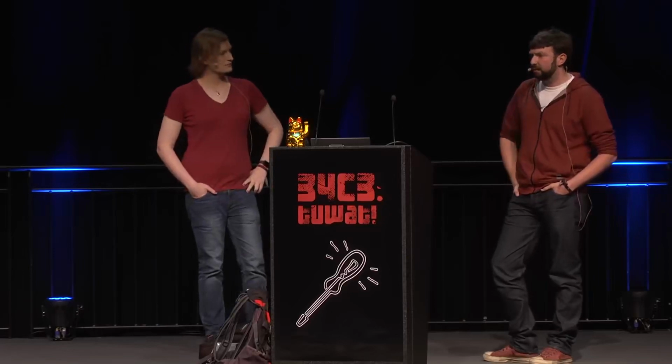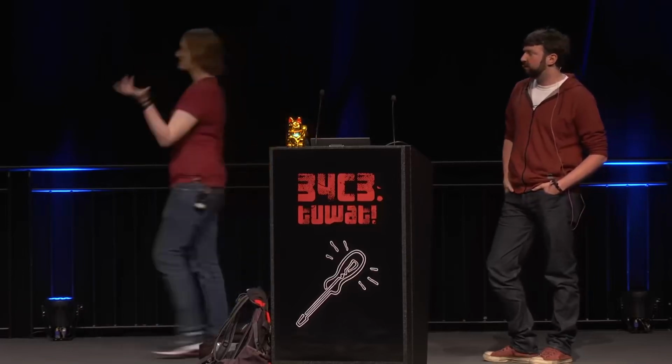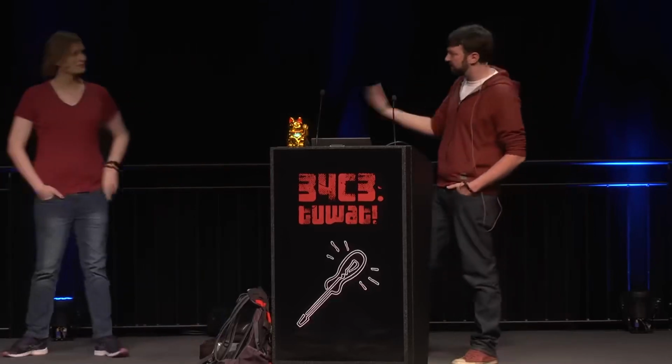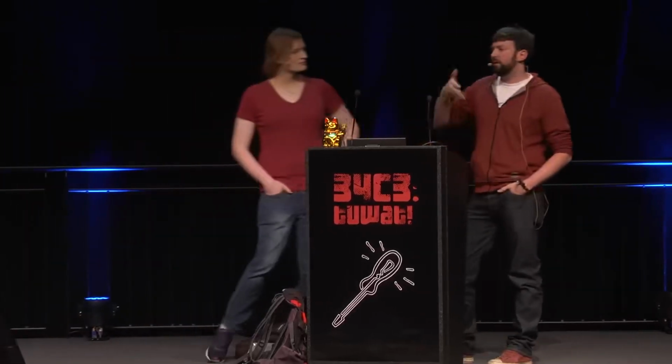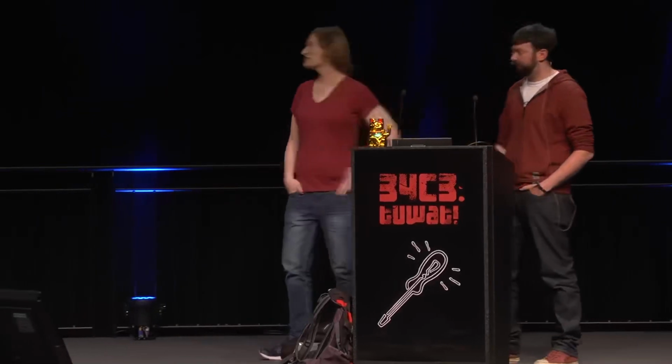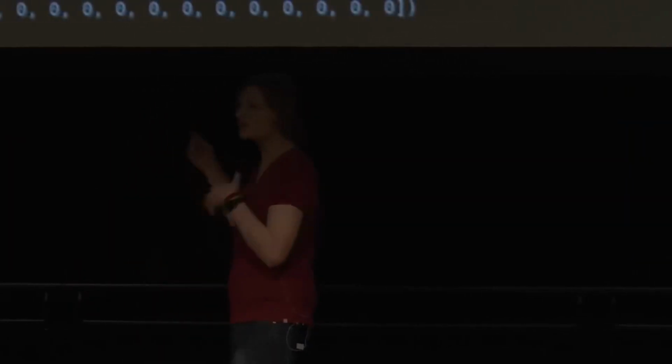And then it'll just start again at the bottom of RAM sometimes. Right, and so we can just keep reading. As long as we can get the DMA controller to do the thing we want, we can get it to keep reading us out. Right. And this is really cool, because if you actually go and ask it for an address that is all the way at the end of RAM, this particular microcontroller has a 32-bit address space. And if I say I want the absolute last byte that's in address space and 127 bytes following it, it will happily read that last byte, and then the 127 bytes it gets when it increments that last address and rolls back around to 0.